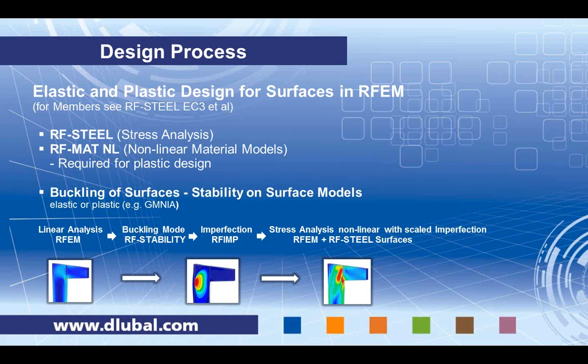If we talk about stability analysis, we need additional modules, RF-STABILITY and RFEM. We can then do an analysis against buckling, and we can do this in an elastic and plastic way. The procedure is to first have a linear analysis in RFEM for a surface model.